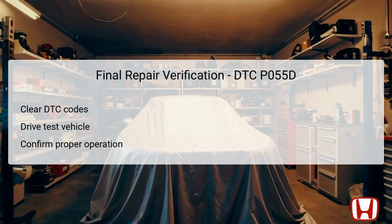After completing all necessary repairs associated with DTC P055D, it is vital to conduct a final verification process. First, clear any diagnostic trouble codes from the system to reset the vehicle's monitoring parameters. Following this, perform a comprehensive drive test of the vehicle under varied conditions to assess its performance. During the drive, observe the engine for any returning symptoms, such as warning lights or performance issues.